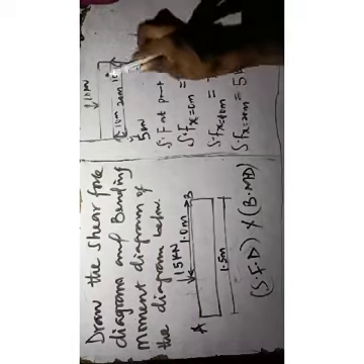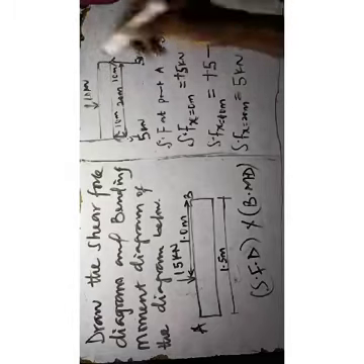Now, be very careful, because sometimes it must come back to 0. Sometimes you can put it as 5 kilonewton, bearing in mind that the shear force is already equal to the force there. You get what I'm saying? That overrules you doing minus 5 plus 5.